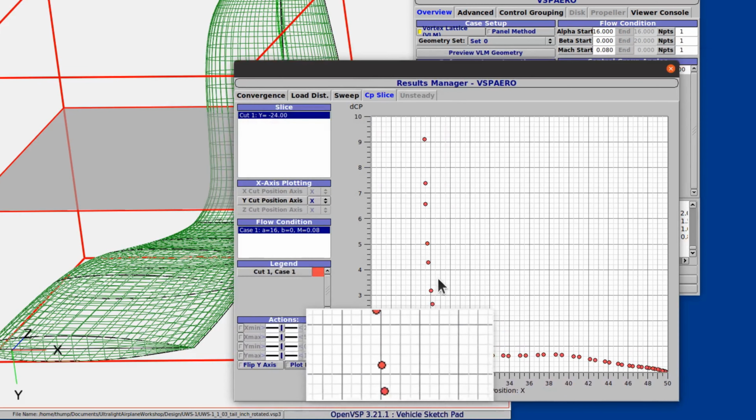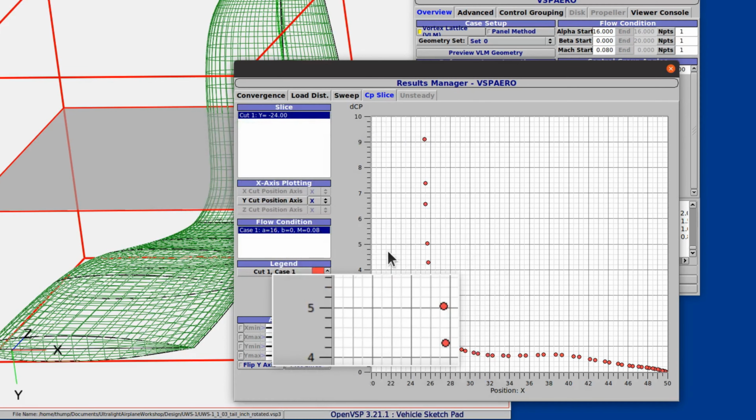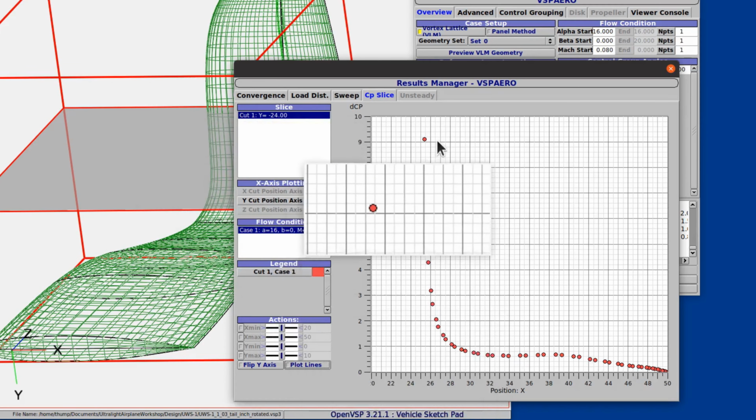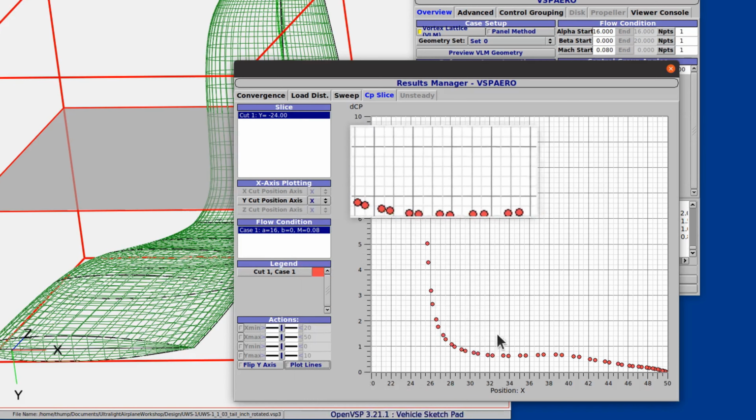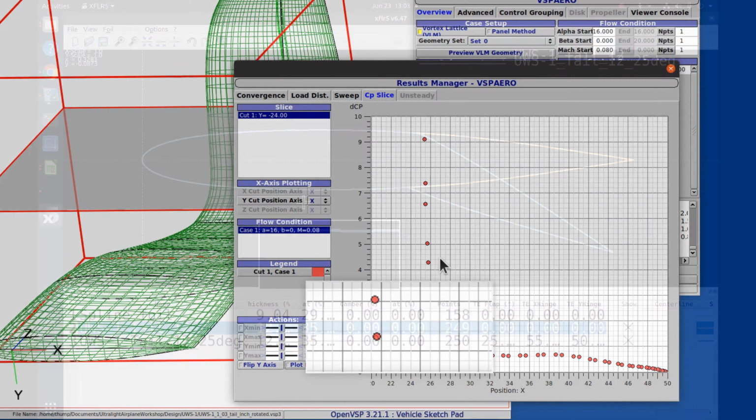This is kind of nice for just doing the chord load across here, but it's not sufficient for what I want. So the next question is then, how are we going to get those coefficient of pressures on the top and the bottom? We are going to use something that we used way back in the past when we were working on airfoils. We're going to use XFLR5.